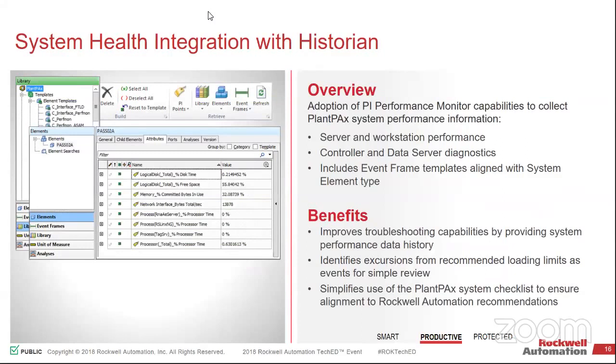What it does is it takes both your ACD file from the controller side of it, your HMI files, your historian files, and your alarming, and you hit a button and it auto-generates a lot of your code for you based on the templates that you decide on. Similar to what probably everybody in this room has done at one point or another. You got a big Excel sheet and you auto-generate all of that code for yourself through XML. This is doing it for you as part of a product design.